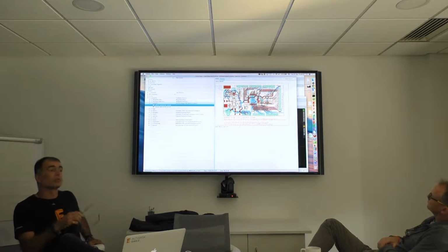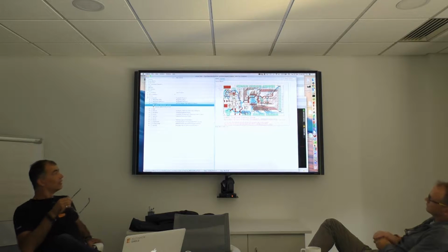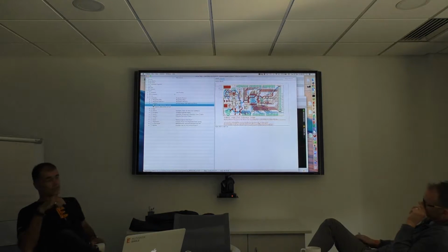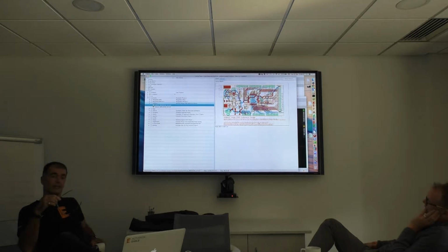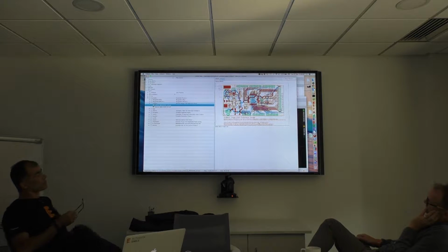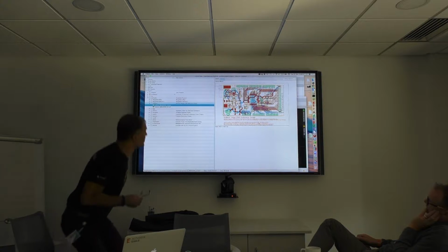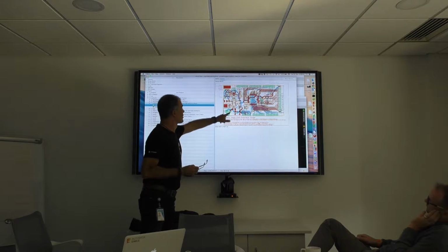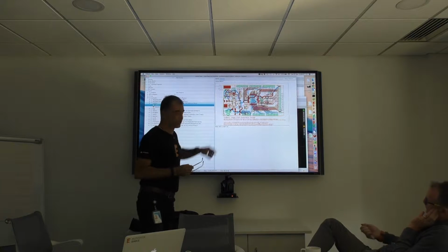If you want to go to mechanics, because you work together with mechanical engineers, then you have 3D models assigned. So you see the components on the printed circuit board. They're represented here. For example, on this one there are 3 big headers, we call them, and there's a kind of connector.